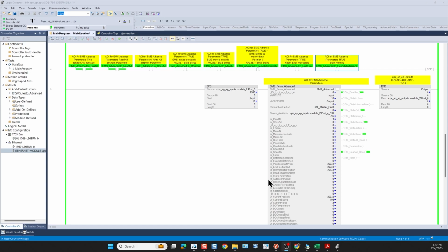Okay, so now we have the current position. It's 20,332. We're going to set the speeds. I would like to use the same for speed out and in, and for the force I'm selecting 8. Default is 1, but I want to have more force to defeat the friction in the slide. And then I'm going to set the positions.